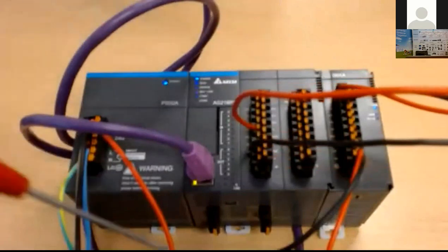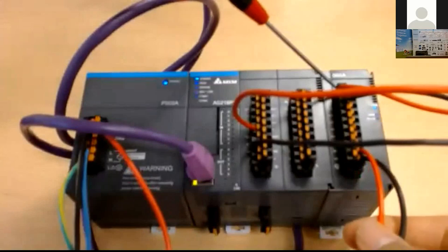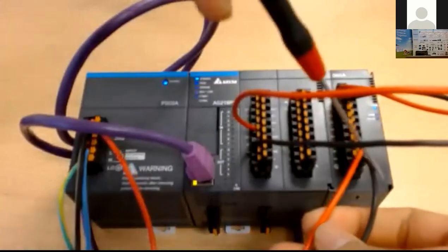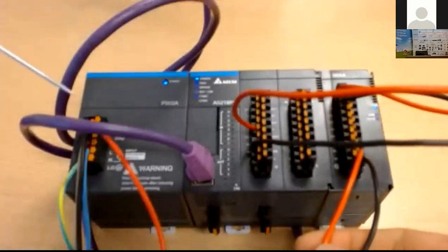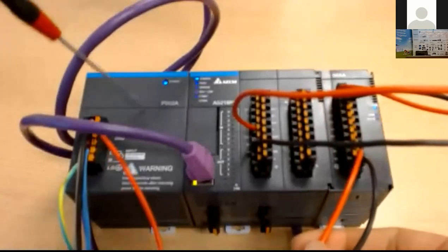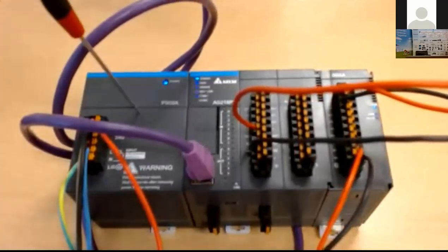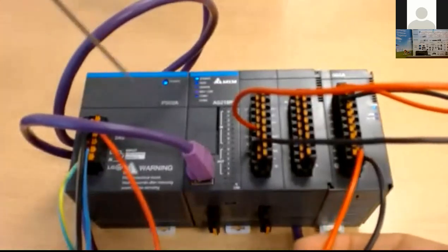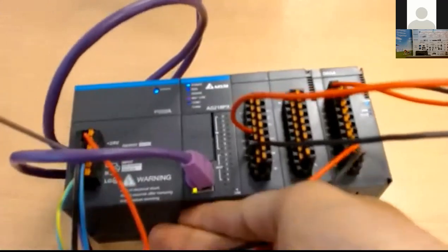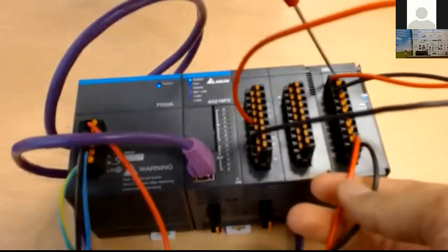And I mentioned to you before that the analog module itself needs 24 volt DC. So these two red and black cables are for 24 volt DC. And actually I got this 24 volt DC from the power supply directly. One of you asked me, is the power supply mandatory? No, it is not mandatory, but as you see, there are some functionalities like this. So I can get an additional 24 volt over here to supply the module itself.